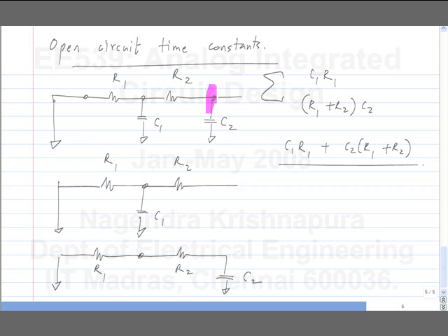If any of you remembers it and this is wrong, let me know. Yeah, that's what this is. Elmore delay model is the method of open circuit time constants. So, the circuit can be represented by a single time constant, which is the sum of individual time constants.